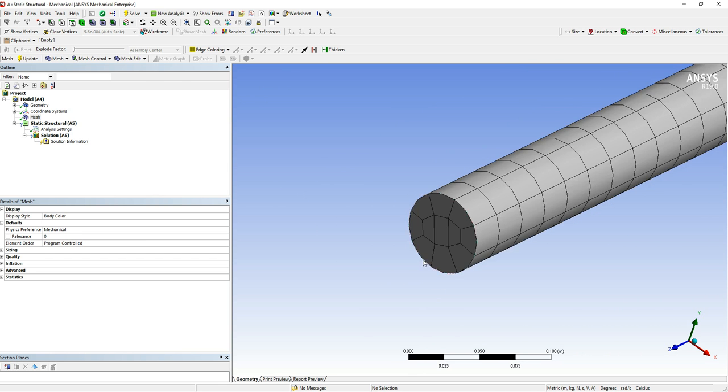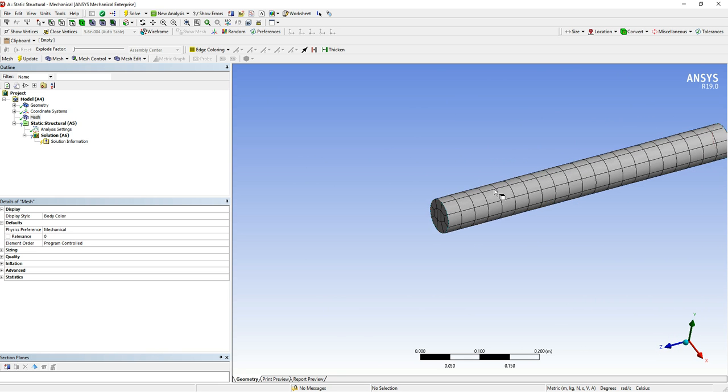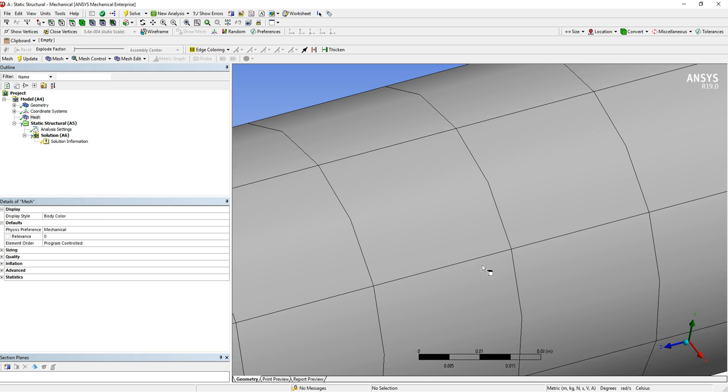We are going to look more in depth at this and at how it behaves. But the basic function is that between each node there is what will be a spider's web thread. Each thread has a representation, which is our Young's modulus. As the node moves, we have a displacement, an original length and a changing length, which gives us our strain. Young's modulus is equal to stress over strain. So we have the basic fundamentals of what we need to know: we know the displacement, the stress, and the strain.